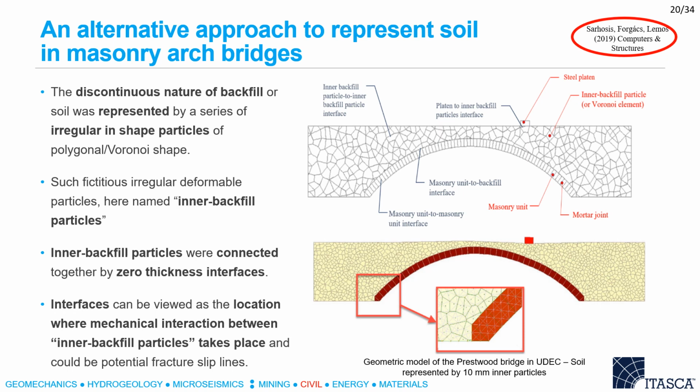laws. The discontinuous nature of backfill was represented by a series of irregular in shape particles of polygonal Voronoi-shape elements. Such fictitious irregular deformable particles, here named inner backfill particles, are shown in figure on the right. Inner backfill particles were connected together by zero-thickness interfaces, which can be viewed as the location where mechanical interaction between the inner backfill particles takes place and could be potential fracture or slip lines.